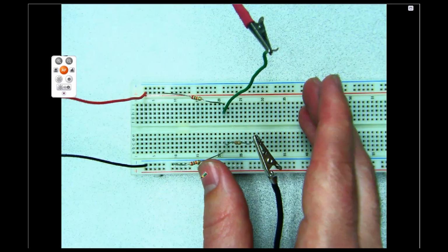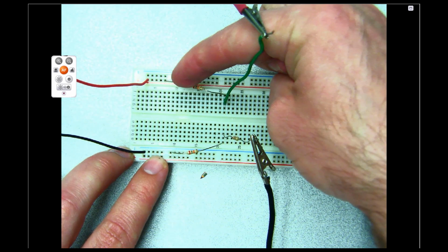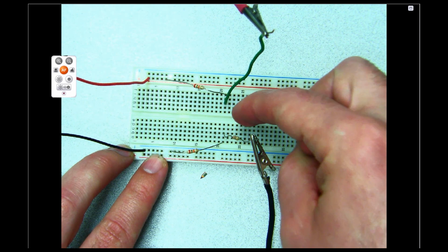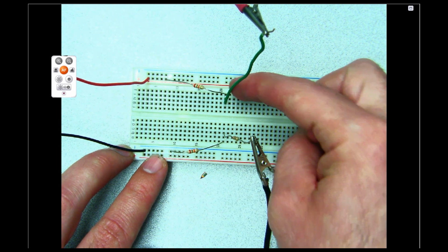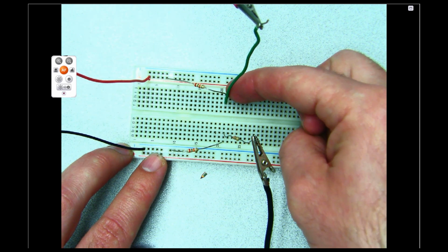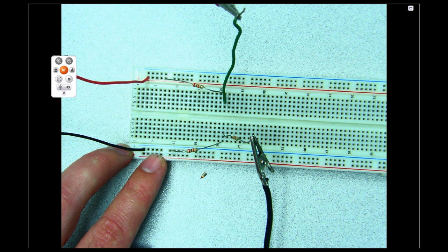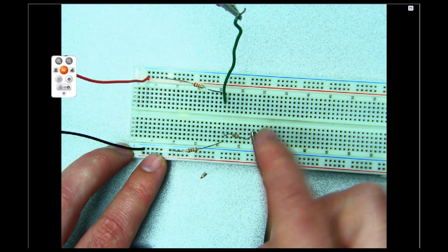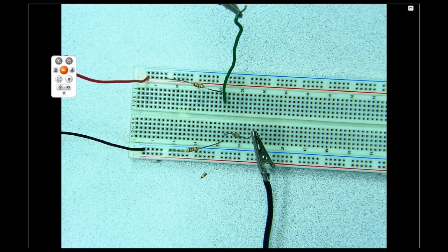And let's look at what this does. What happens is that the current that used to flow from this resistor straight into this resistor here and then onto the rest of the circuit now has to flow from this resistor and then up through your meter where it gets measured, and then back down here, and then it continues through this resistor and continues on through the rest of your circuit. So you're forcing that current to go through your meter and get measured.